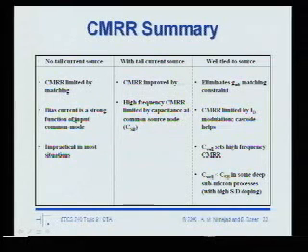So without a tail current source, yes, we're limited by matching. Something I didn't say is another problem with this circuit: what determines the bias current when we ground the source node? The input common mode signal determines the bias current. That's pretty bad, right? You want the bias current to be constant, not a function of the common mode input.